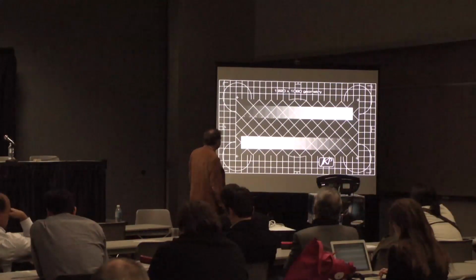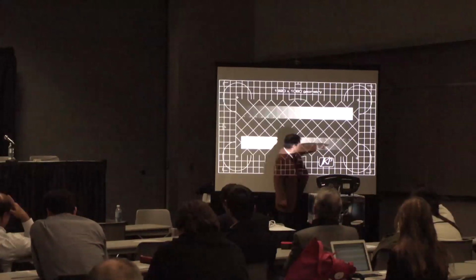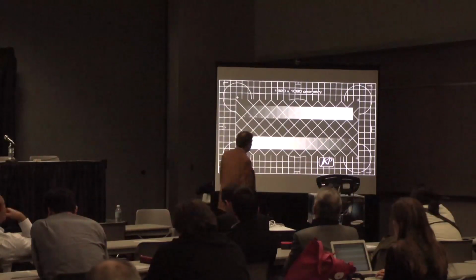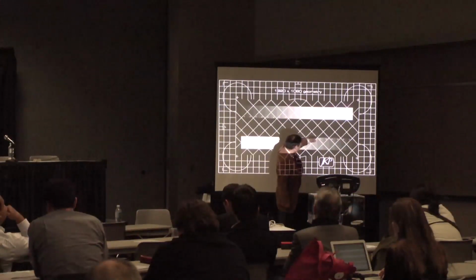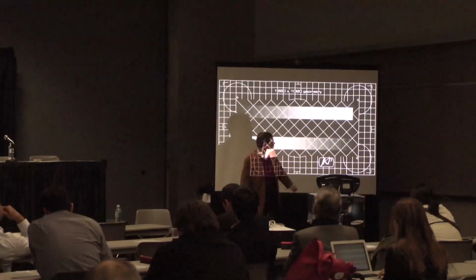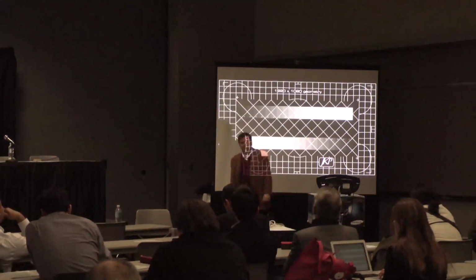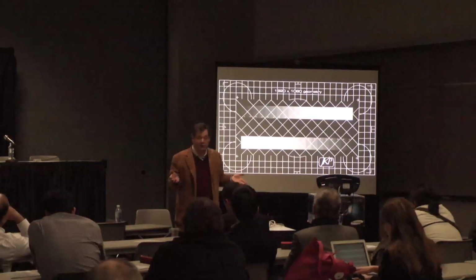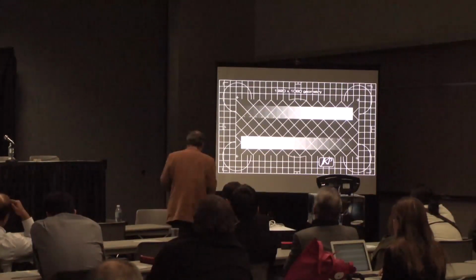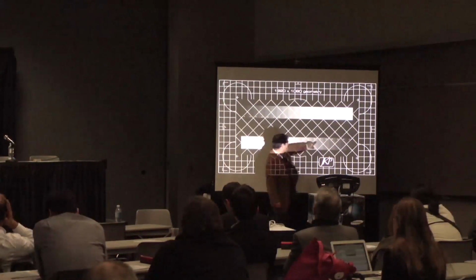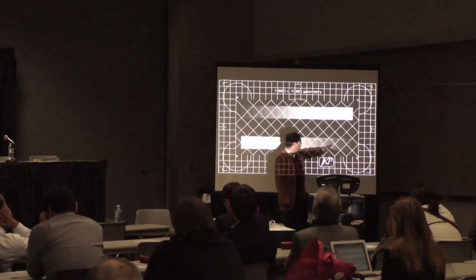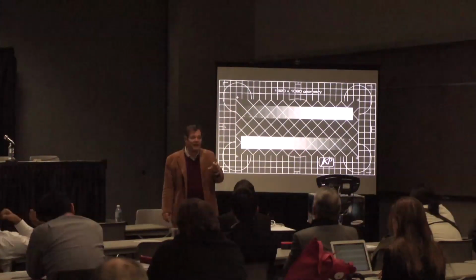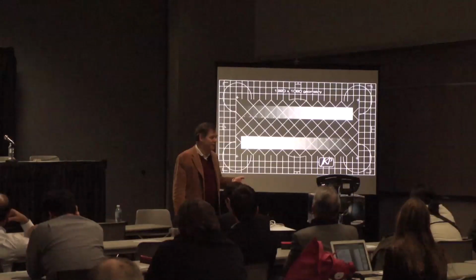So what I end up doing is the ghosting crosses the grayscale. Now this is just a simple approach, but the ghosting crosses the grayscale, and there's a point where the ghosting disappears because the level approximately matches the level that's behind it. So I can tell, okay, there's 30% ghosting. The amplitude of the ghosting is 30% of the primary, because when the line crosses over here at 30%, it essentially disappears, or when it crosses on 25, it essentially disappears. So within 5%, I can get a quick idea of what the percentage of the ghosting is.